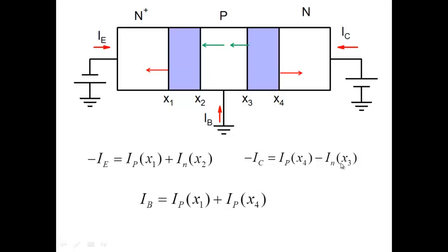I will get that. So implicitly, what if I assume that this current is the same as this current here? What does this represent? Electron current. So what we are saying is whatever electron current is here, the same is the electron current here. And why? Because there's no recombination. Right? So there's an implicit assumption when I write this that these two currents are the same here. INX3 and INX2 are the same. Because whatever electrons are coming to the base, they don't recombine, so the same must be at the other end also.